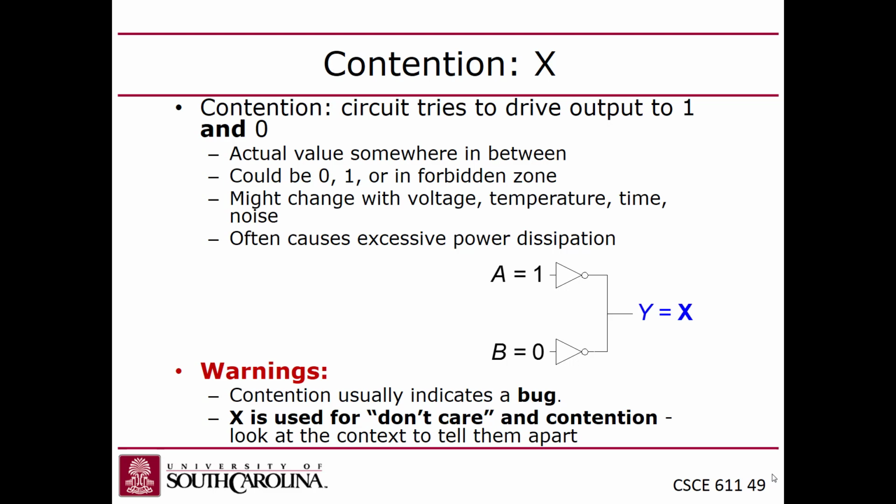You guys with me? So instead of just having 0 and 1 for a binary value, they introduced this x, right? And x means there's a problem. But it's also a third value that a signal can take on when you simulate your circuit. And there's actually 3 reasons why you would have an x in there, right?